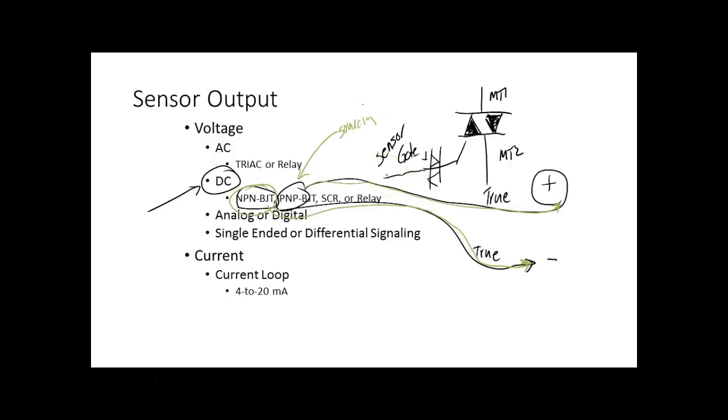The problem is that when you look it up, they don't say sourcing and sinking. They say it's an NPN sensor or a PNP sensor. So it's up to you to know the difference. A PNP sensor is a sourcing sensor. An NPN sensor is a sinking sensor. Whether you understand about NPN and PNP transistors doesn't really make any difference in this class. If you take the solid state class, which is one of your core classes if you're ILT, you'll learn about NPN and PNP transistors. All we need to know in this class is which type of DC sensor you have. Everybody okay? Yes or no?